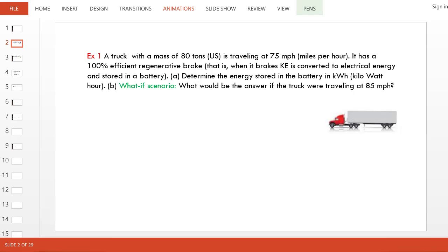Well, we all know the formula for kinetic energy. We all learned that in physics. But if you use the SI unit for mass in kg and V in meter per second, you're going to end up with a unit of joule, which is a very small amount of energy in engineering thermodynamics. So we always express energy in kilojoule. That's our standard unit for energy. To do so, we divide by 1000. So the formula becomes mv squared divided by 2000.